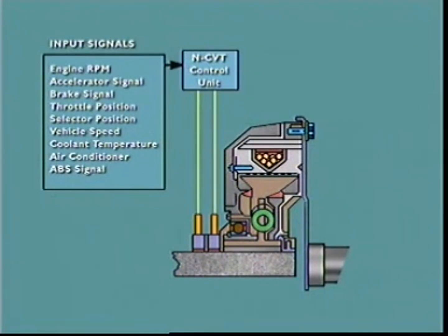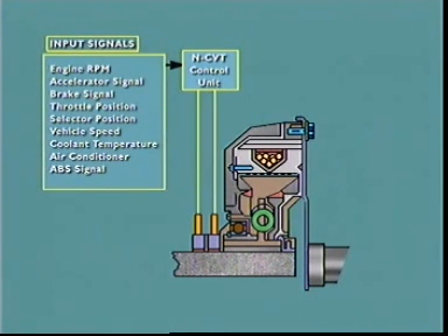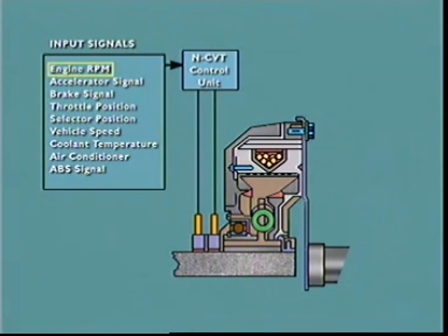Clutch current is controlled by a transmission computer, reacting to input data about vehicle operating conditions. At idle speeds with the vehicle stationary, current flow is small, which allows slippage between engine and transmission. As the accelerator is depressed, the computer delivers more current to the coils.